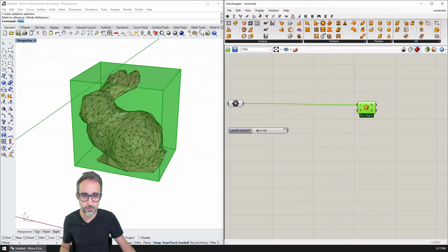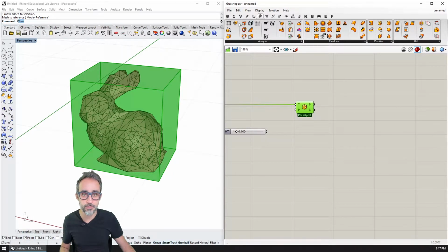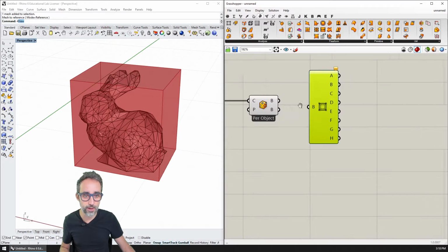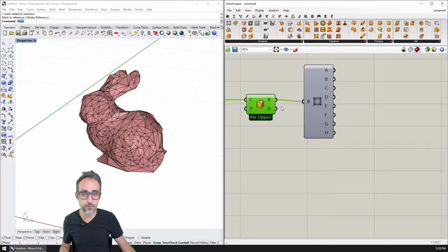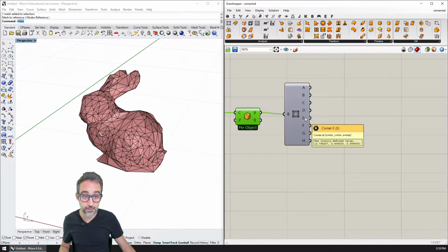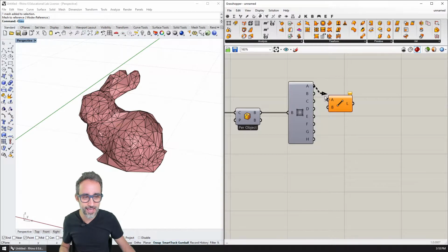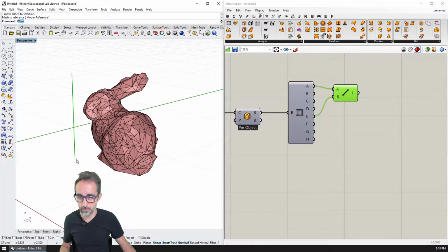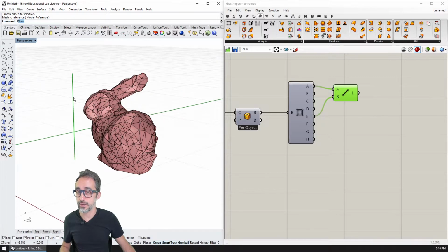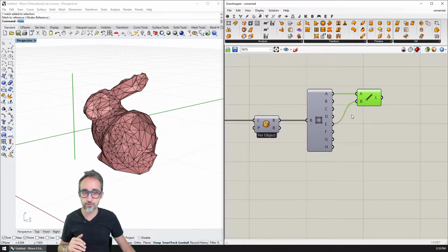So that's going to be one thing. And then I'm going to decompose the mesh into a wireframe. And then I know that the A and the E, because I did it in the previous exercise, not because I remember, are the 2 points that are here on the bottom left side of the box, so that I can create a vertical line that represents the height of the element. And then what I would like to do is populate this with XY planes at a controlled distance.